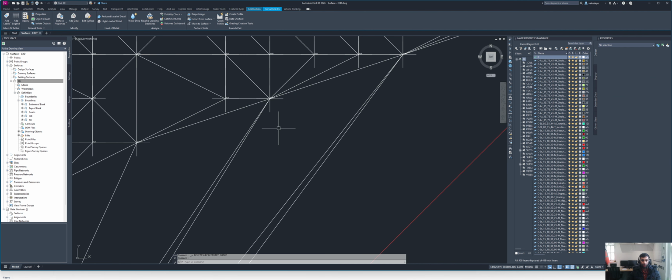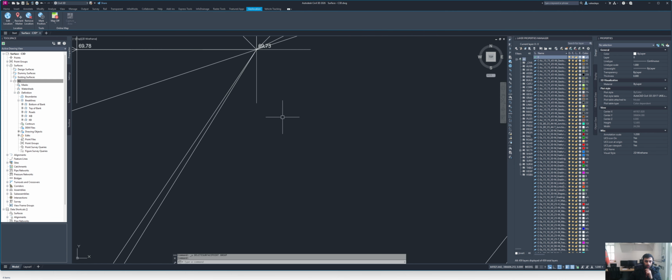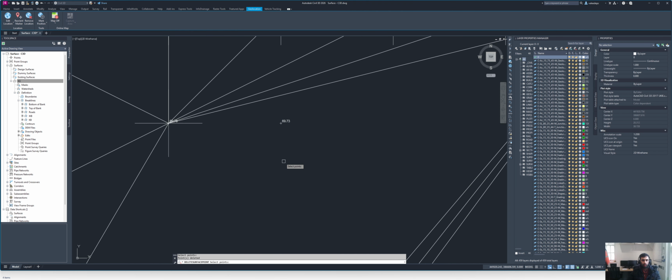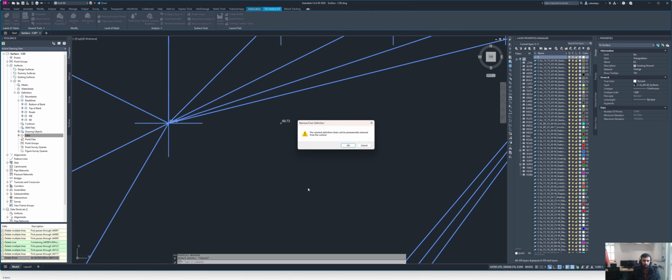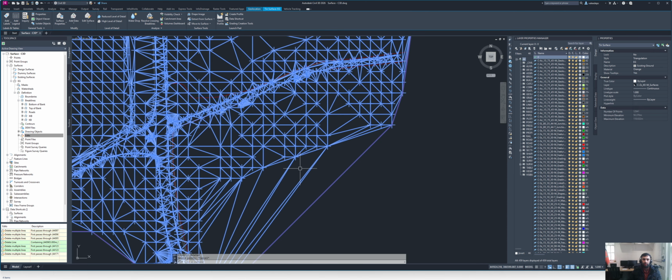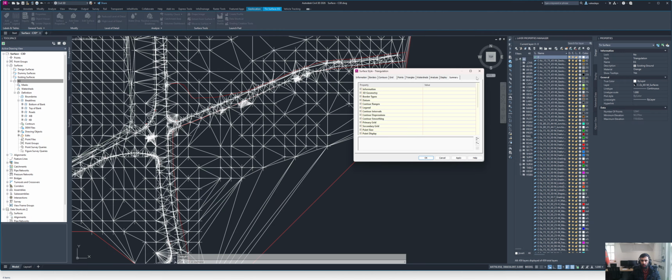So now where is this point? Now I will just use undo. I will try to delete this point, select this one, escape. Now you can also see in the edits you have all these ones. So you have seen that you have deleted a point here. So if I right click and then delete, your point is back here. So this is how you can edit your surface as you are required to do.